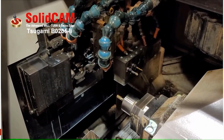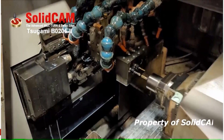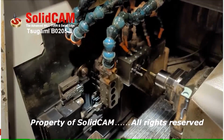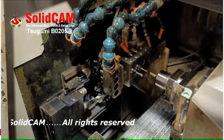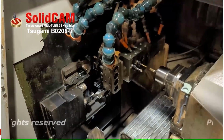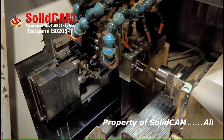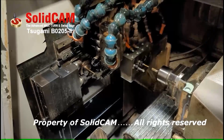This programming was done on a Tsugami B205-2 machine. In this video, you'll see that we want to verify the axes alignments are correct for each turret. The arc directions are coming out properly, and you'll also want to test that the milling functionality works in planar as well as with the fourth axis engaged. Another one of the most important factors of proving out the code is making sure that the part pickoff and eject processes are coming out correctly.